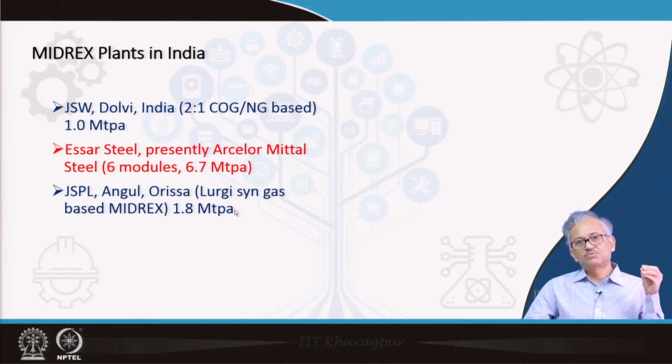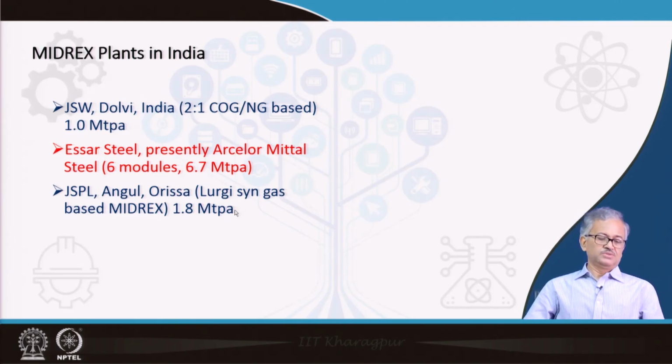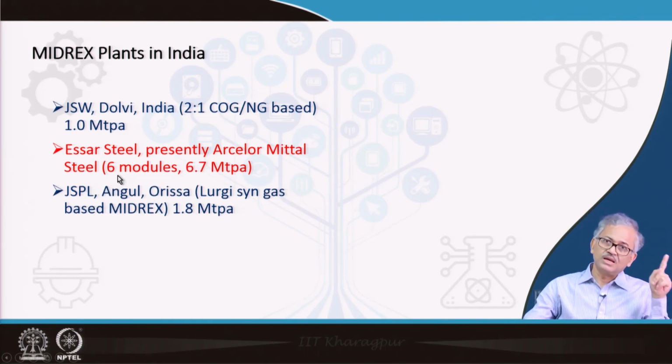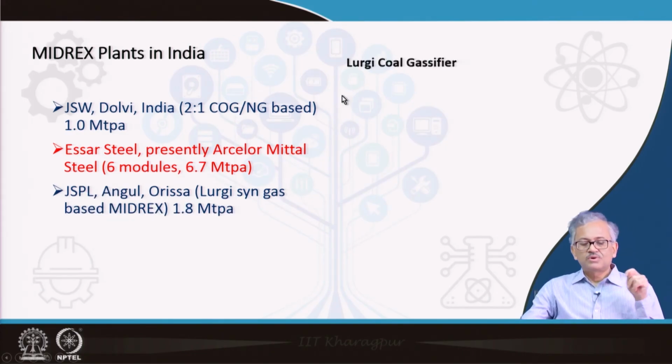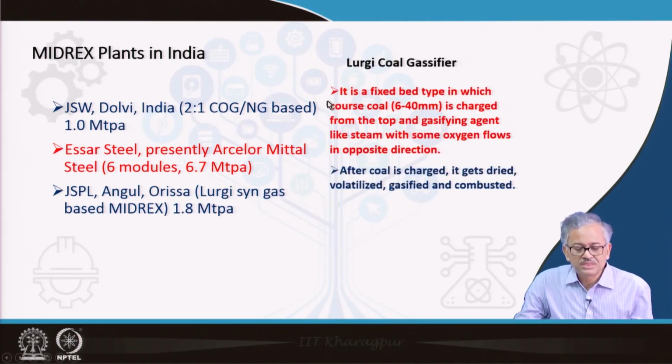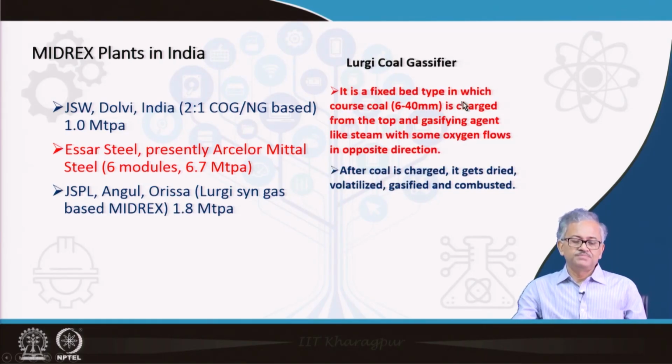How? Basically the coal is gasified into syngas, and then synthetic gas is used in the Midrex reactor. Okay. So basically it is Lurgi based syngas, there is the Lurgi syngas based Midrex unit. So it is a coal based Midrex unit, it is not a gas based Midrex unit. Okay. I am talking about the Lurgi coal gasifier. Basically it is a fixed bed type.